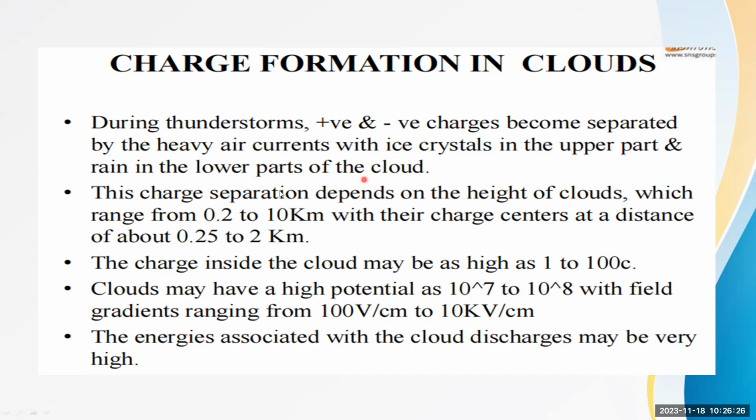The charge separation depends upon the height of the cloud, which ranges from 200 meters to 10 kilometers, with the charge centers' distance about 250 meters to 2 kilometers, or 0.25 kilometers to 2 kilometers.